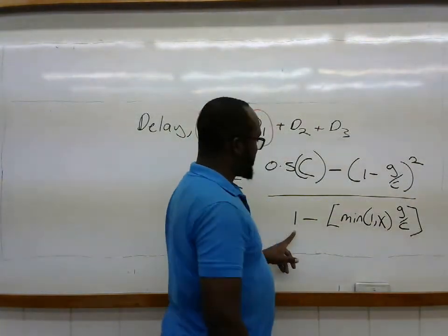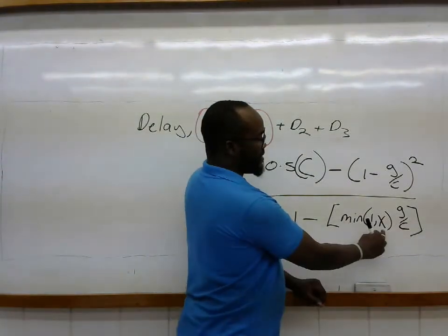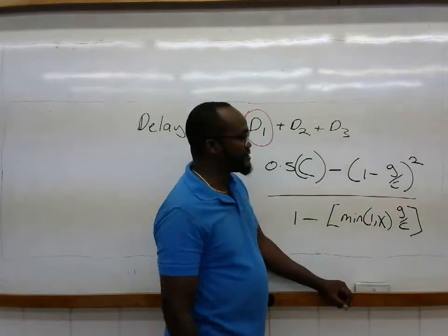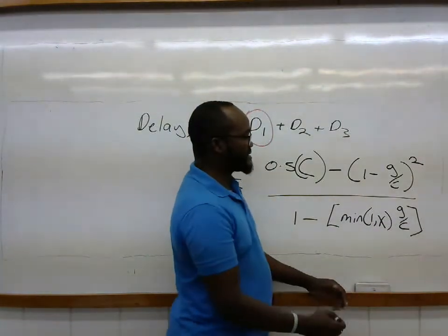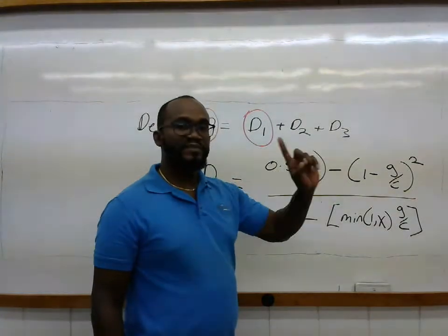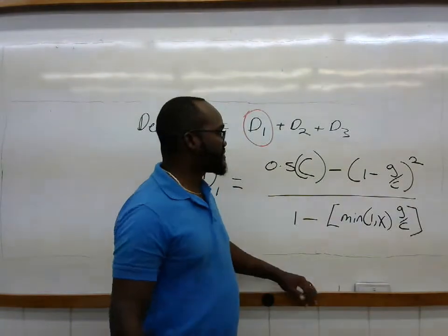This is then divided by 1 minus the minimum of what we call the V upon C ratio, or volume to capacity ratio, given as V upon C. Again, the volumes that you would have computed in a particular direction divided by the capacity, which you will work out subsequently.